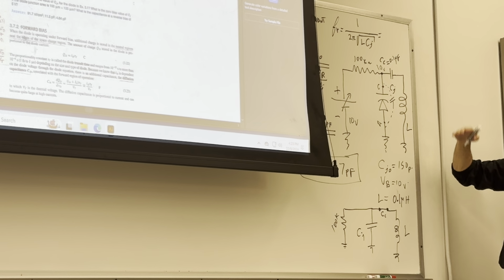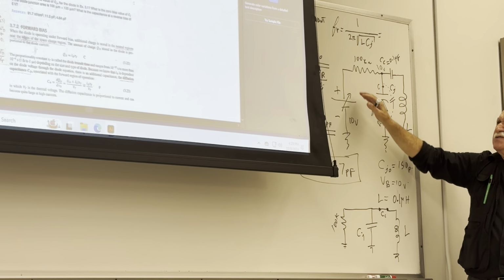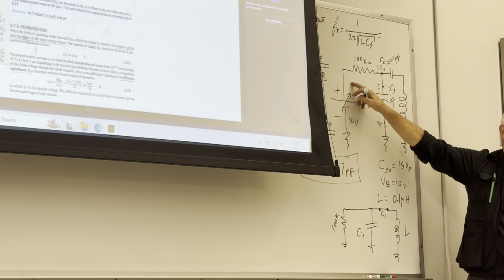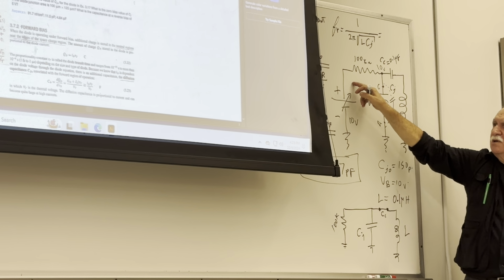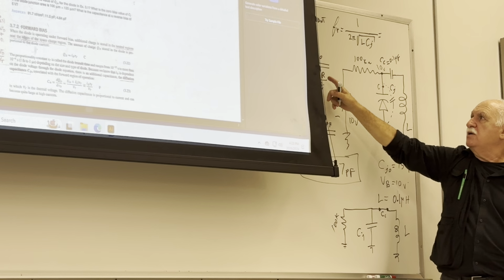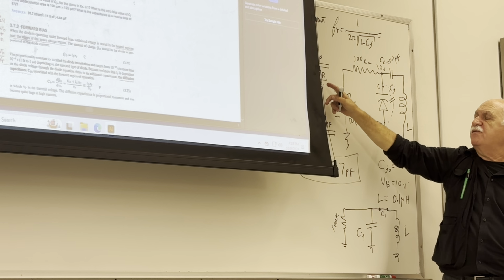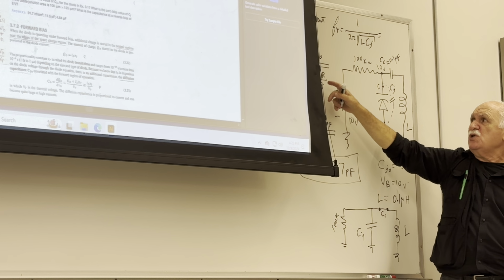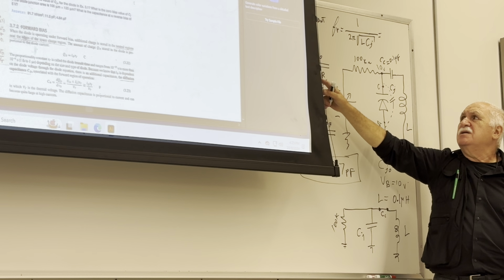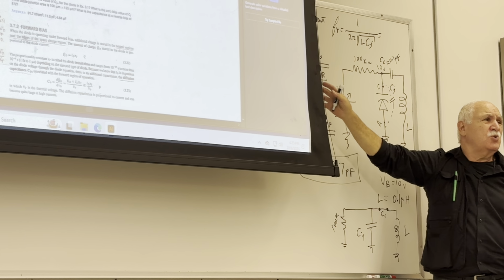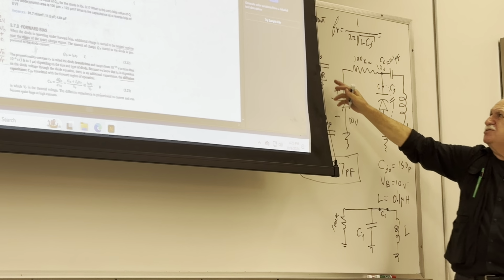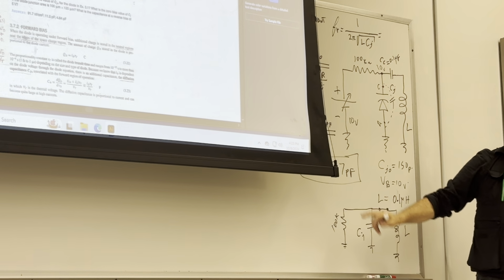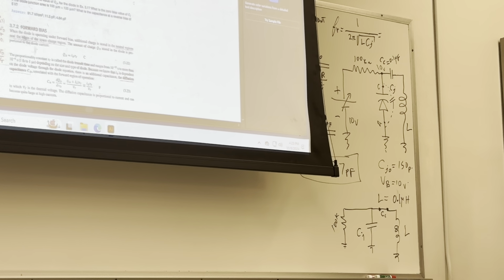The maximum will be where this voltage source is very, very close to 0. Maybe 1 volt. If you go to 1 volt in here, it will be 1 over half, 2 plus 1. Radical 3 is almost close to 1. So you'll get just under the 150 picofarad. So it will be adjustable from a largest 150 picofarad all the way to a few picofarad, 1 or 2 picofarad.